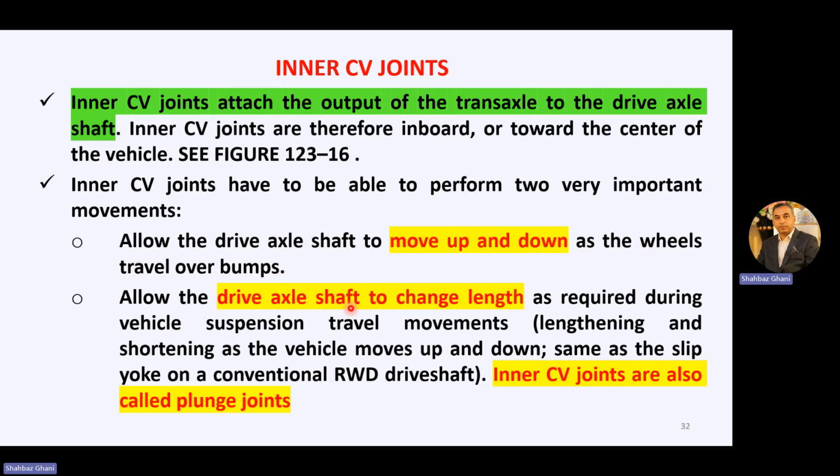Allow the drive axle shaft to change length as required during vehicle suspension travel movement, means in and out, lengthening and shortening as the vehicle moves up and down, same as the slip yoke on a conventional rear wheel driveshaft.